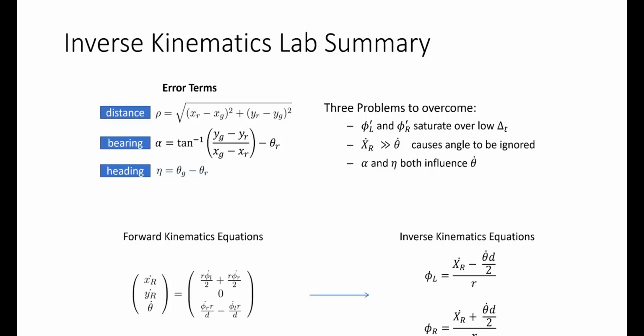Oh, okay, can we fix the bearing error before working on fixing the distance error? Absolutely, that is completely a design decision that you will make. So one way to set up your controller is to have your coefficient behind your bearing error be really high. So again, like 1,000 times bearing error. And that's going to make theta dot really big, and that will pretty much force your robot to turn in place, right? Or turn with very little displacement once you do the correct proportionality of it.